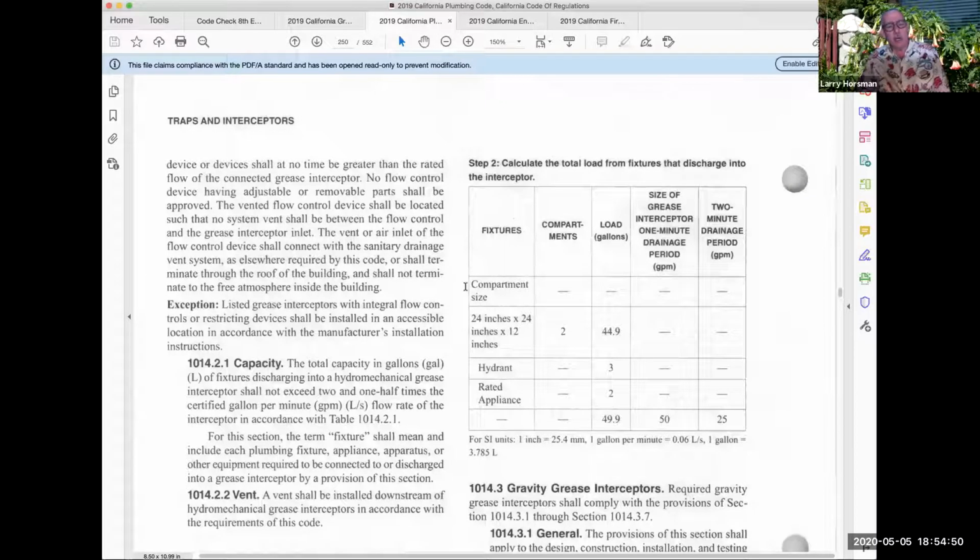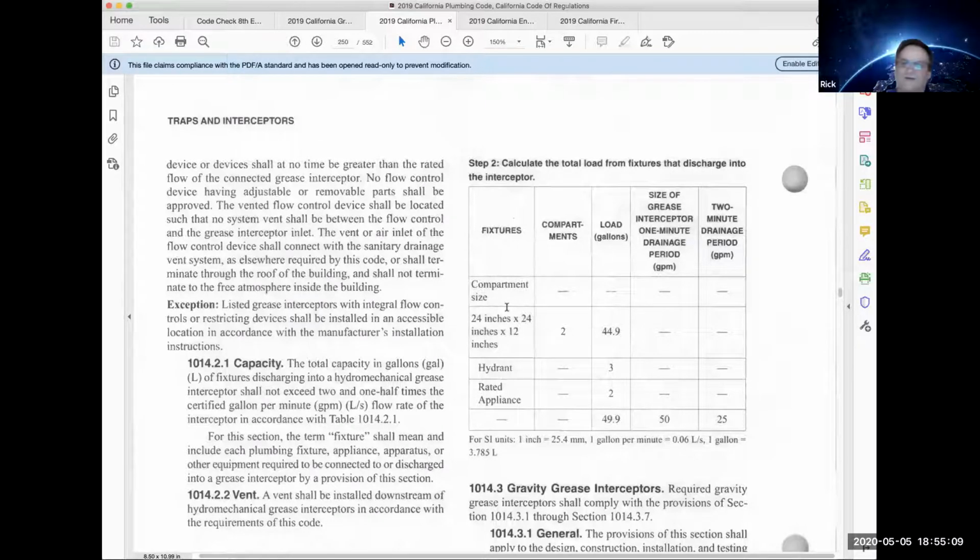And if you go in there, it will walk you through, depending on the type of establishment and how much grease it's generating and how many meals they serve per day. And so they ask you a bunch of questions, and then you get a little report you can submit to the building department. For sizing the grease interceptors? Yeah, for sizing the interceptor. And if you want, they'll actually work with the building department.